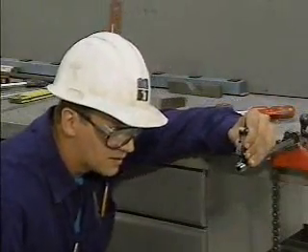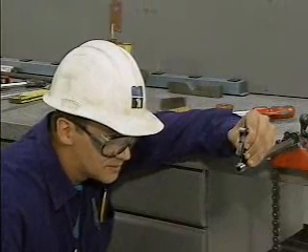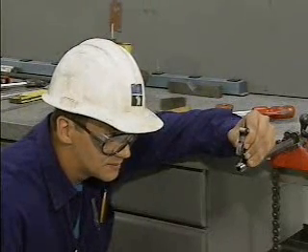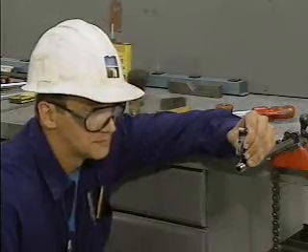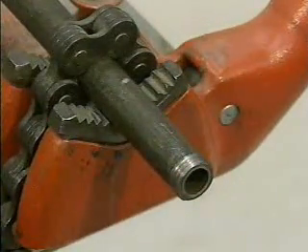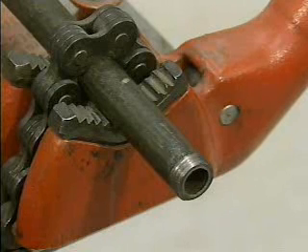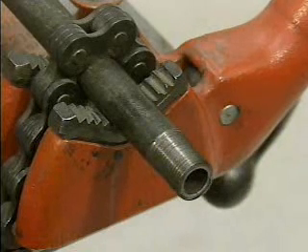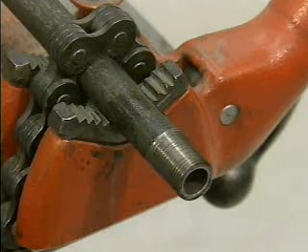You can use a thread gauge, such as this one, to calculate the number of threads per inch on an existing pipe or fitting. The final consideration when you're threading a pipe is the length of the threads. Threads that are cut too short will be weak at the joint and will leak. Threads that are cut too long will make creating a joint difficult, which may also cause a leak.